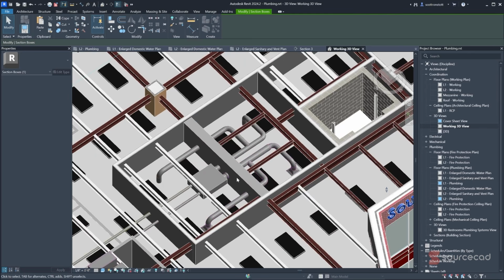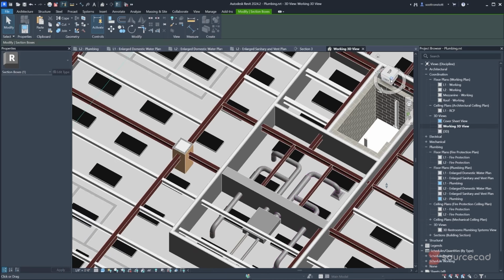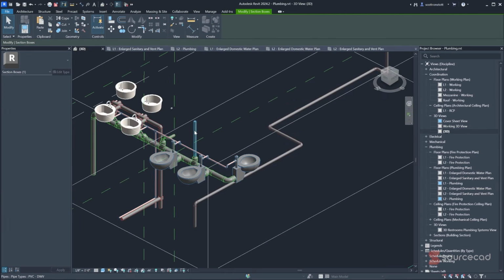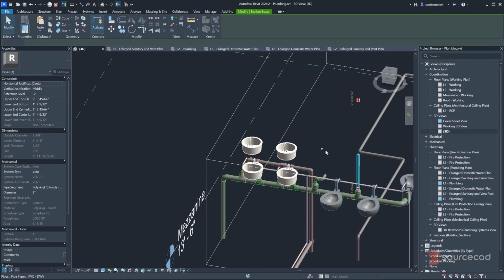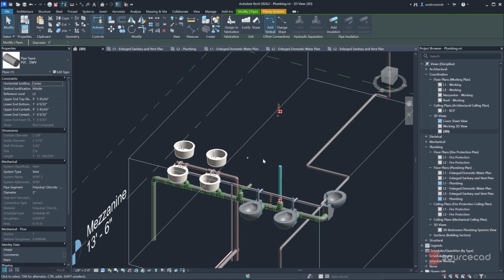So here's where I need to bring my vent over. I think I'm just going to run it over this way and then connect it over here in the chase. Yeah. So let's see. How can I do this? I need to look at my 3D view, and I want to bring this up higher. I know I won't be able to draw that up vertically in the 3D view, so I need a better angle on it. I need a section.